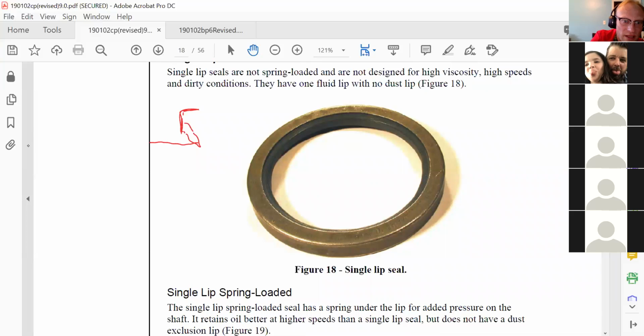And it will seal against the S-cam. Here's your S-cam here. And then you fill this area with grease. It pushes against the lip, which seals tighter to stop grease from coming out. And now if you remember when you're doing brakes, one of these you typically put in backwards, right? Yes, you do.